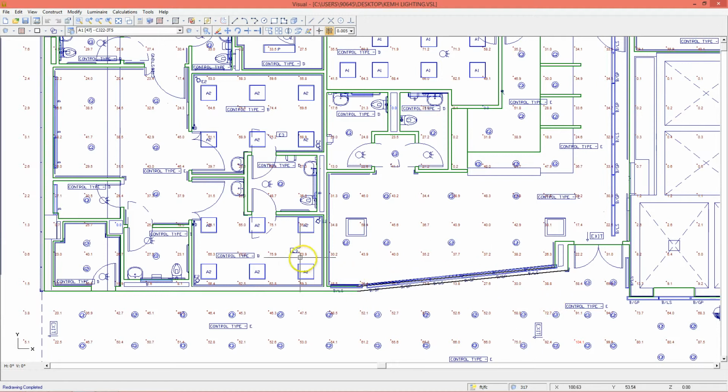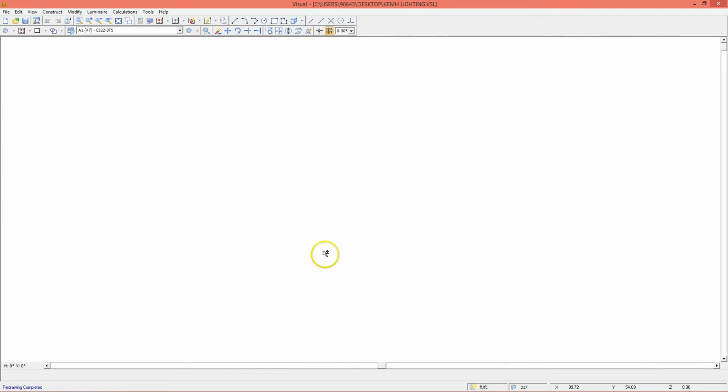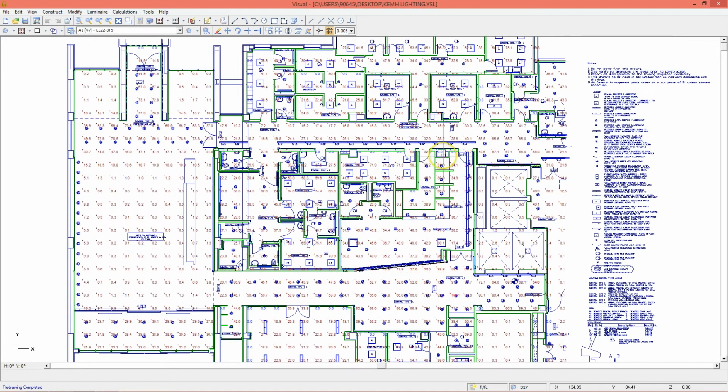Obviously, in different rooms, you'll get different readings simply because different lights are used. In this area, we were using a 2x2, much more intense light than just a 6-inch recessed. We were achieving around the 750 lux level, so quite high lux. Now, obviously, in a hospital, certain areas need very intense lux levels or foot candle levels, whereas other areas don't require as much.